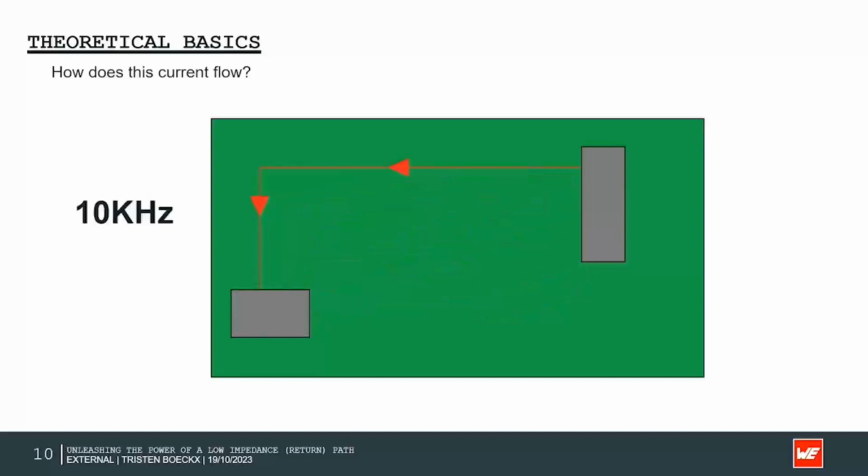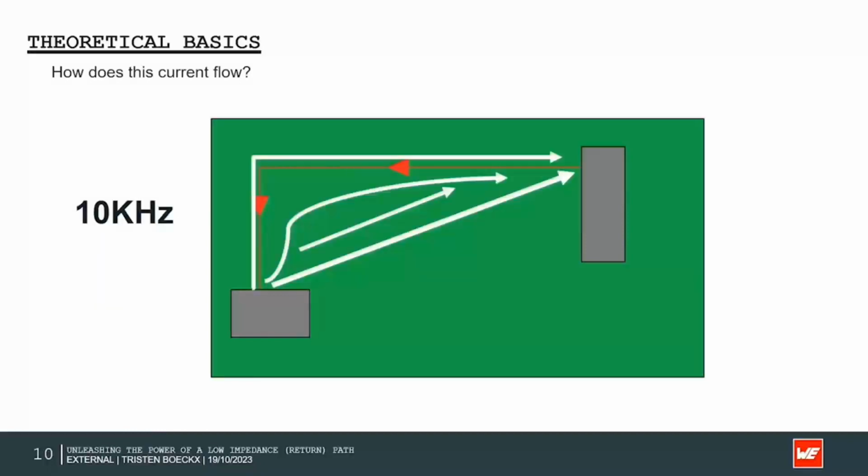Further, when we increase the frequency, we can also see an increase in the return currents flowing below the signal path. This is due to the higher frequency, at which the inductive part also shows to be more dominant. The path of the least inductance or impedance is the shortest loop area, and this is of course below the signal trace.